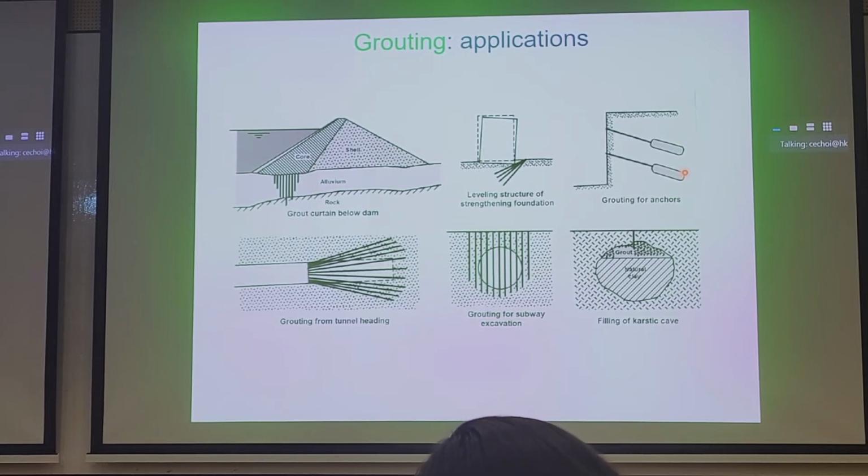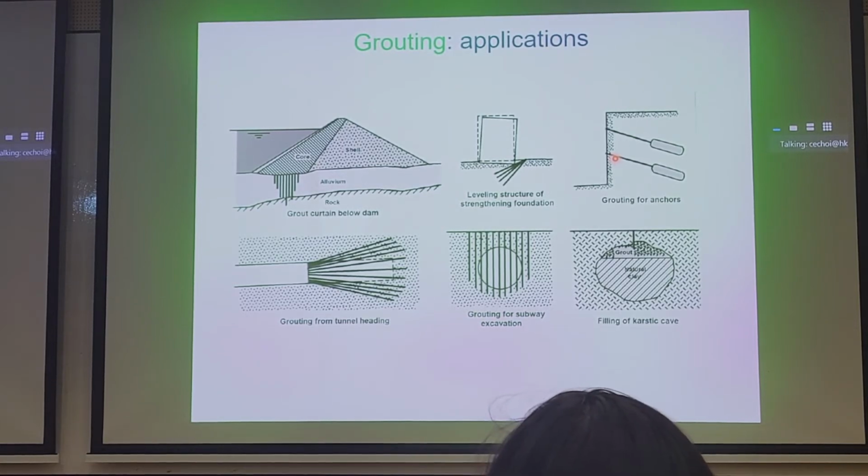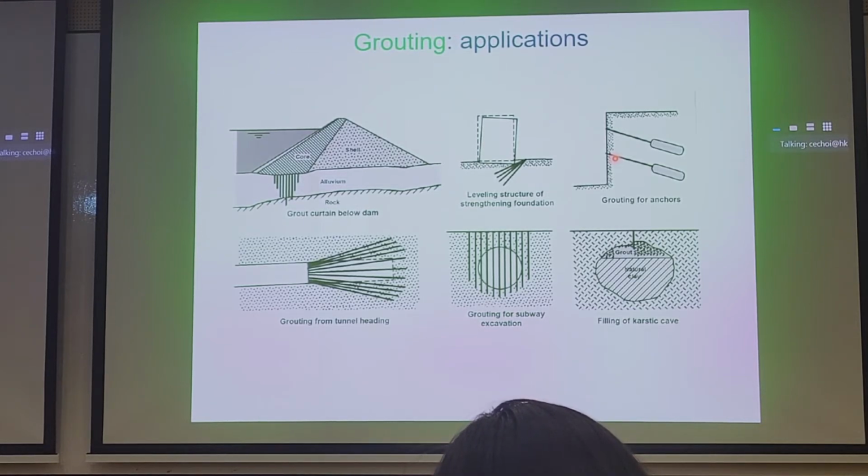Soil nails look very simple as well, but they differ from ground anchors in that you have a fully grouted steel tendon. We don't carry as much stress per soil nail, for example. You rely on the composite bulk effect of a lot of nails in the ground to stabilize a slope. Soil nails are mainly used for slopes. Ground anchors are more commonly used to stabilize, let's say there's a retaining wall here, we're trying to pull it up as we excavate.